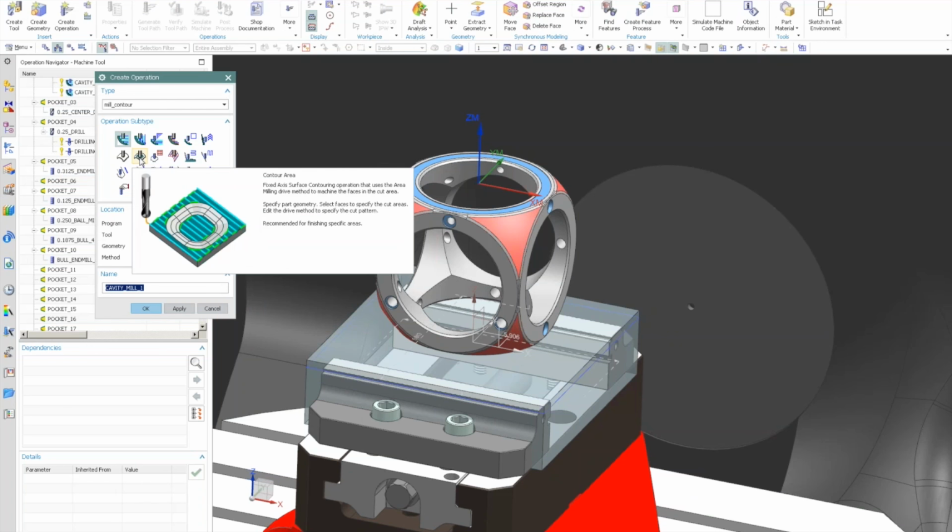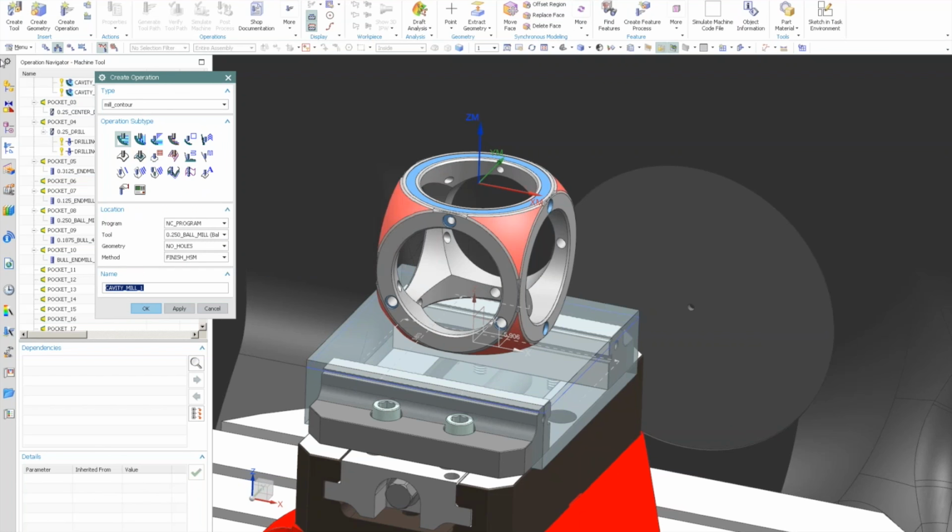There are two. We have one called area mill and one that's more like a streamline. Streamline is like having two flow curves and maybe some cross curves, for a part that has a boundary you want to follow. It's a very cosmetic part, so it'd be nice to have the toolpath follow those curves that someone in ID or styling spent a lot of time to make pretty. But area mill I think would work well in this case, so I'll go ahead and pick that.